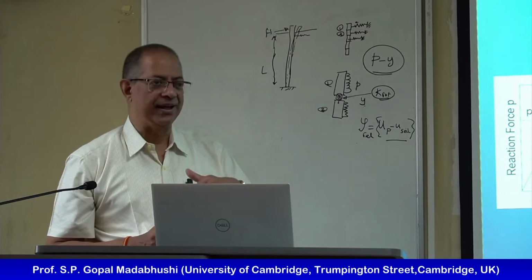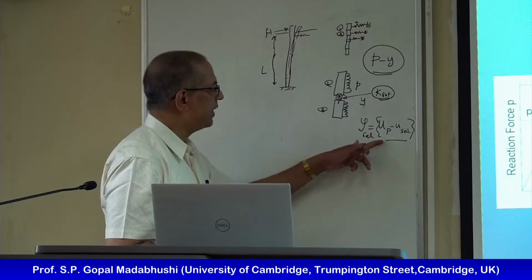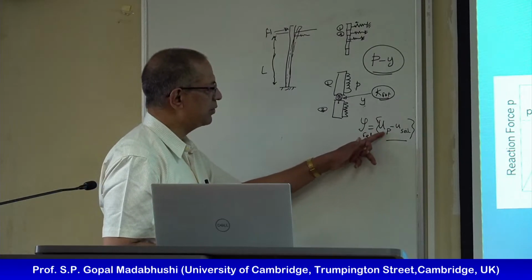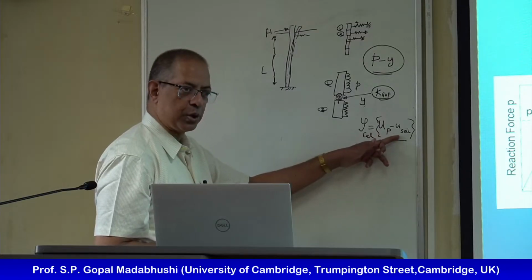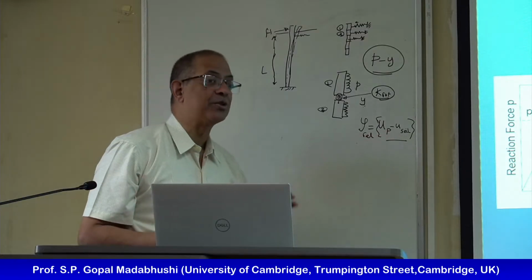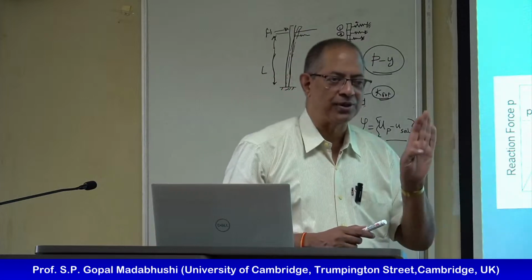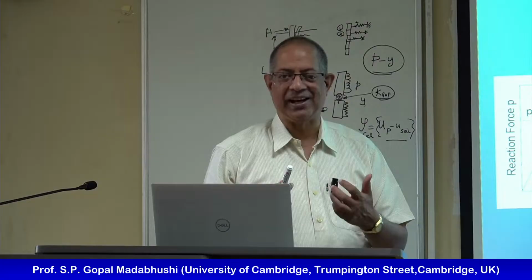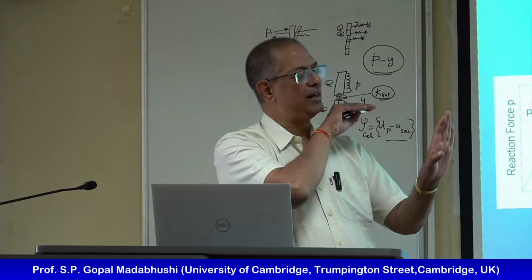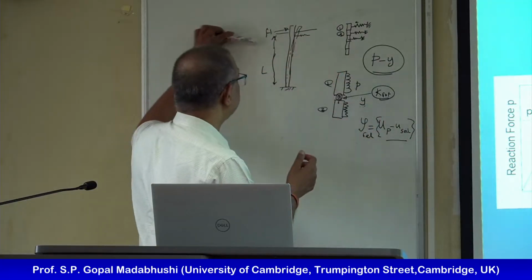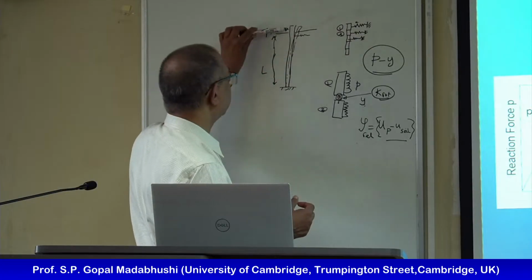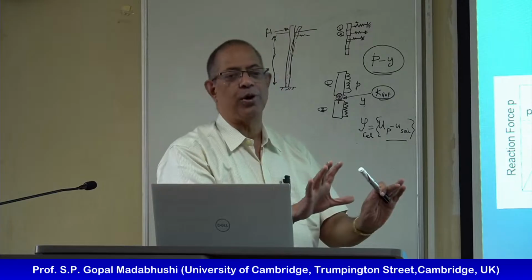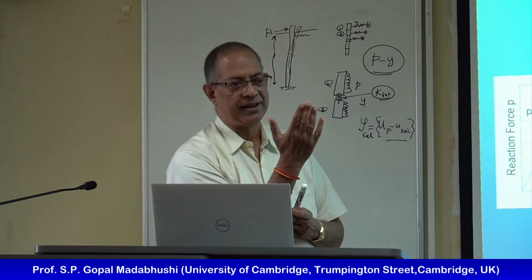The only thing here is we may get this deflection of the pile and deflection of the soil. If my soil is walking down the slope, then that's going to be a lot bigger than what the pile can do. So if my soil is coming and attacking the pile this way, it's not that I'm applying a horizontal load, but I'm applying a big soil pressure that's causing the pile to bend.